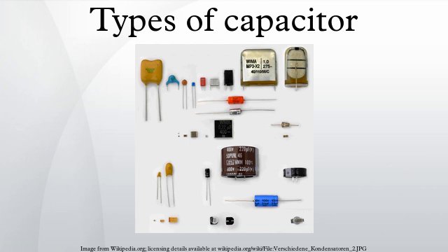Using a series equivalent circuit instead of a parallel equivalent circuit is specified by IEC EN 60384-1. Standard capacitance values and tolerances. The rated capacitance CR or nominal capacitance CN is the value for which the capacitor has been designed. Actual capacitance depends on the measured frequency and ambient temperature.